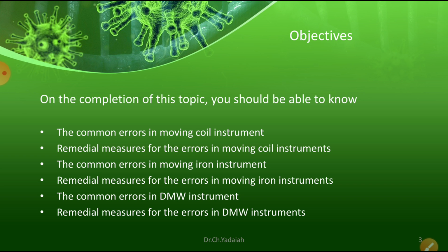I squared R T by J heat will develop. This heat will change the resistance of metals. We know that all metals are positive temperature coefficient metals. If temperature increases, the resistance also increases. If resistance increases, the current value decreases. If current value decreases, the flux decreases. If the flux decreases, deflecting torque decreases. Then there is an error in measuring instruments. That is the link with temperature.